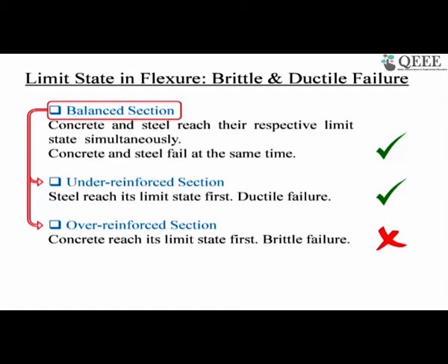There are different reasons for size effect. There is a statistical size effect, and there is an energetic size effect. We won't go into details. But the important point is that the strength does not remain the same. If you use it in an actual structure, it gets reduced, so we need to reduce it. Now it is observed over the years that the reduction is about two-thirds of the strength that you obtain from experiment. That's why 0.67 is taken.